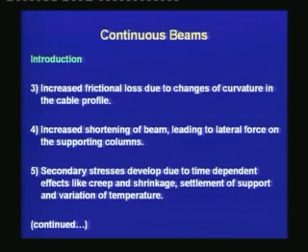These effects cause stresses in the structure, whereas a simply supported beam is a statically determinate system. This does not have secondary stresses due to the settlement of the supports or due to the change in temperature.